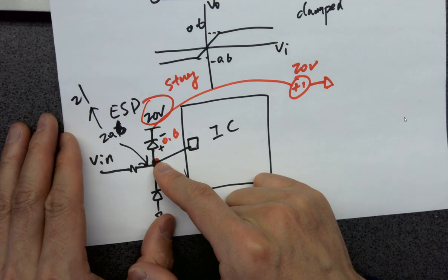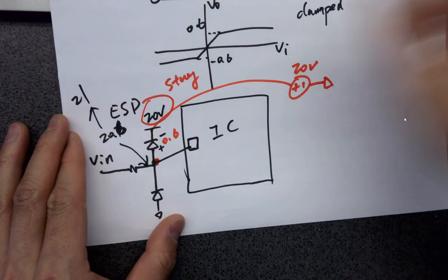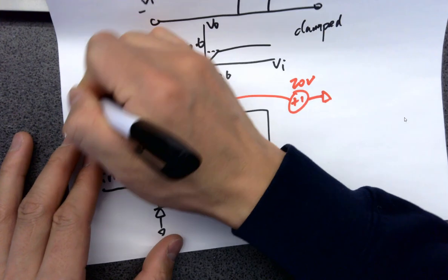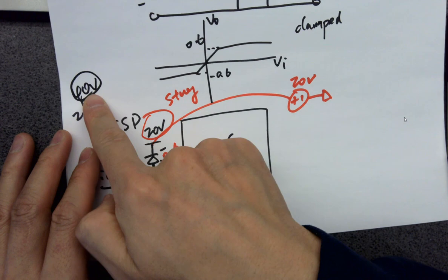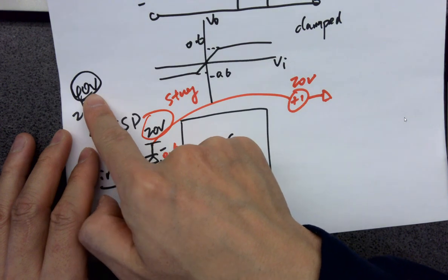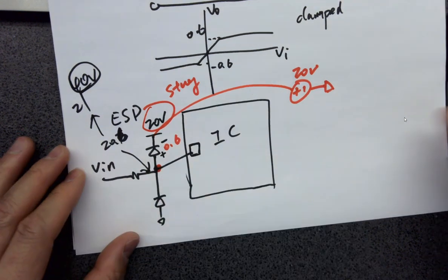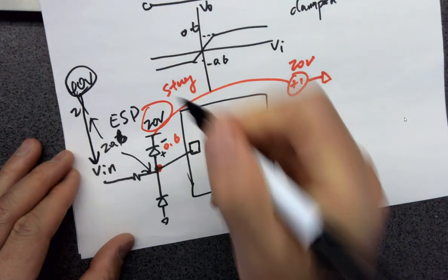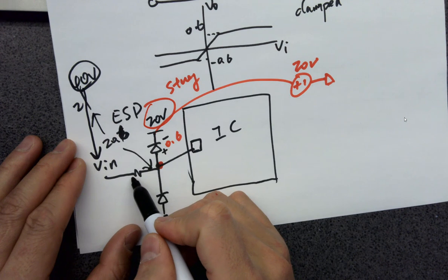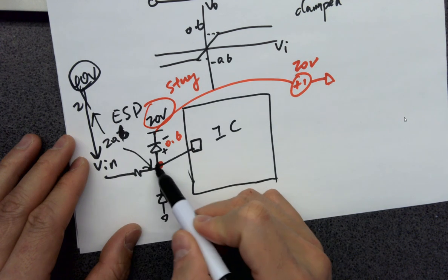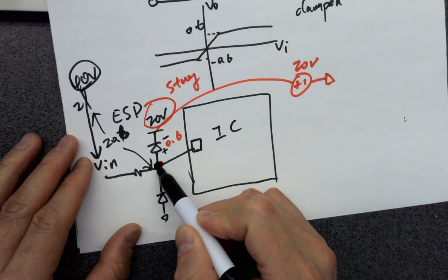You're asking, how is that possible? If I got a surge like 40 volts, it's a surge, okay? What's the voltage? I mean, 40 volts for V in, but there's a resistor to drop the voltage. But eventually, the voltage at this point will not be higher than 20.6 volts.